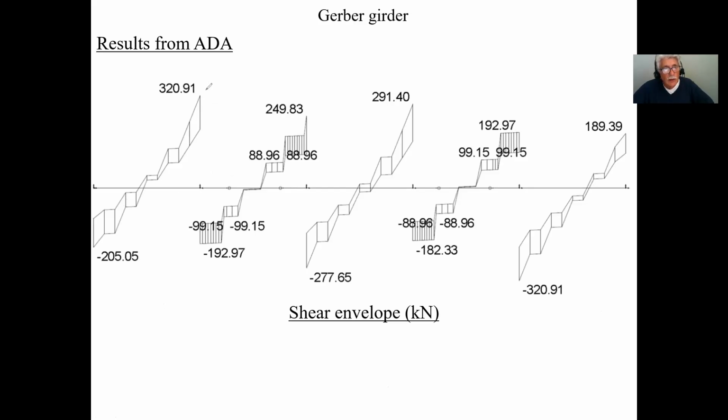Okay, so guys, remember, this is the shear force. So in other words, this is going to be a continuous member from there to there, and therefore this is going to be the maximum VF. So whatever you choose here, it's going to be a W610 by something. Well, then you're going to have to check that VR is greater than that VF value.